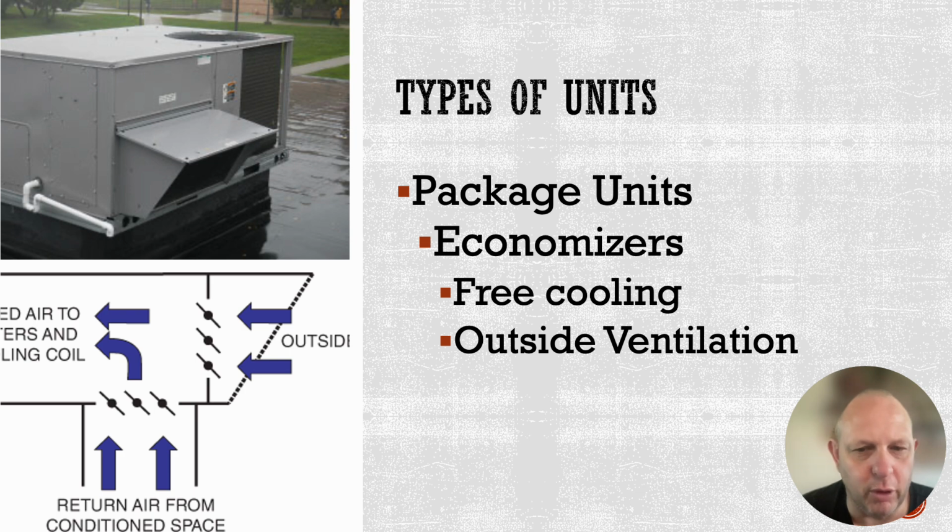So we're going to use the blower. We're going to suck in the air from the outside, and then we're going to dump that air into that environment. We have to be wary of the amounts of humidity that's in the outdoor air because we don't want to dump a bunch of humidity into that environment. Otherwise, we're going to defeat the purpose of what's going on.